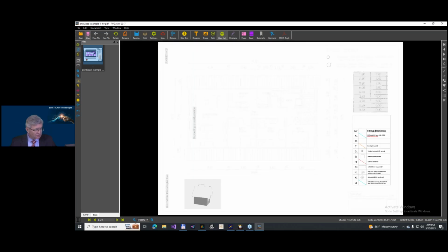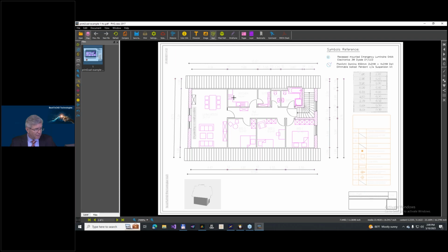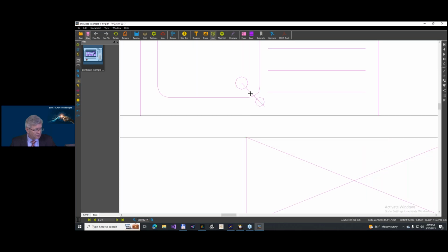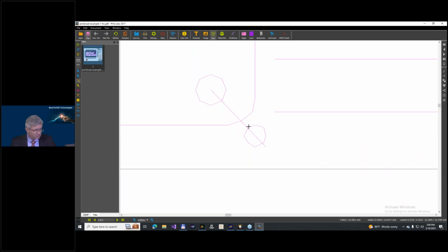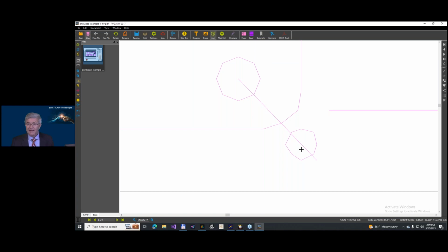You can also see this bad quality if you go here on path and zoom in on details, like these 2 circles, you see? And this is a big disaster with PDF files, because if you import these files into CAD systems, you will get something like this. What happens if you want to recognize this as a circle?